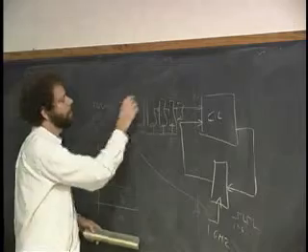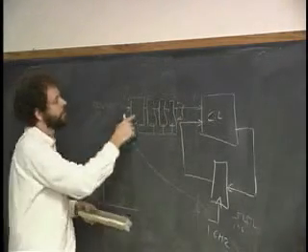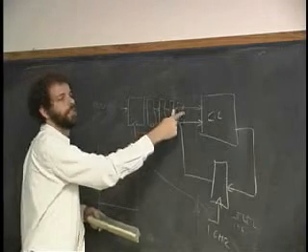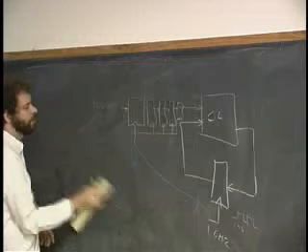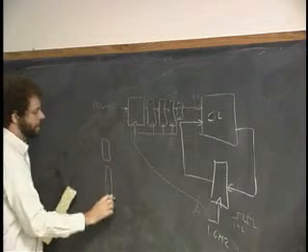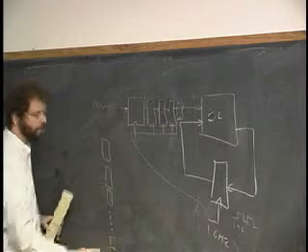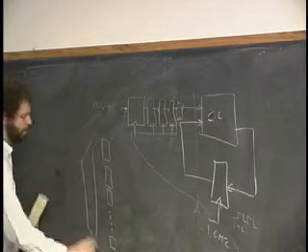And so I can build myself a pipeline of flip-flops like that and basically hand off the task to the next flip-flop in the assembly line to get the job done. That's one way to do it. Another way to do it, which is equally valid, is I can have 100 flip-flops like this, okay? And I can have a decoder over here